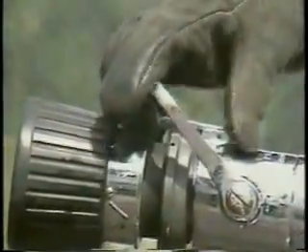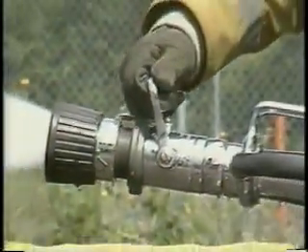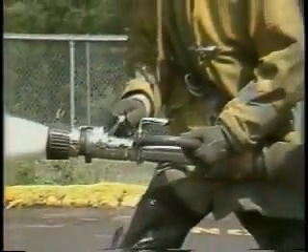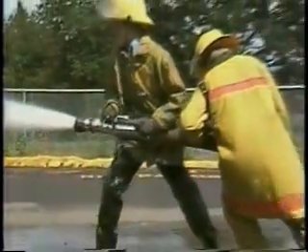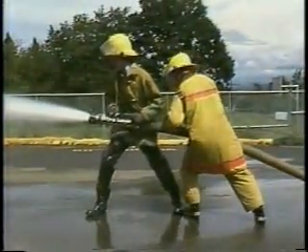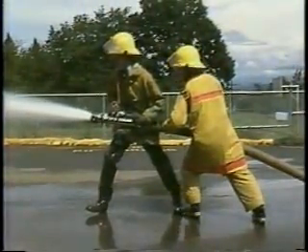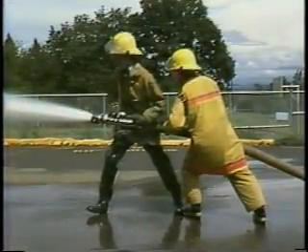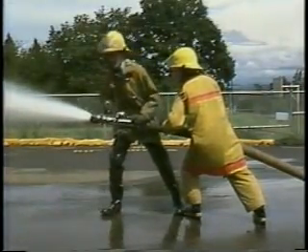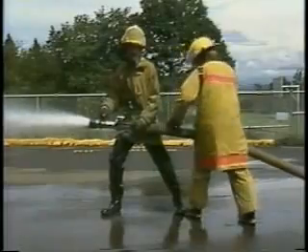And nozzles, when opened, exhibit a recoil effect as pressure is released through the nozzle. Nozzle operators should secure the hose and nozzles with straps or hose rope tools to assist in controlling the recoil effect and to maintain a grip on the hose. It's also desirable to have a backup person stationed behind the nozzle operator to help in controlling the line.